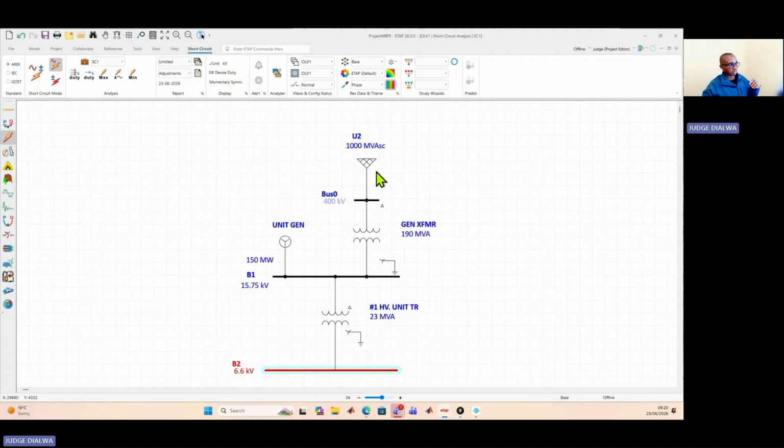And I think this is really smart because ETAP doesn't take those as occurring at the same time. It takes these as two independent scenarios. So I faulted bus B2. We'll run the short circuit study. Mind you, our hand calculations gave us 19.748, and that is what we have here.